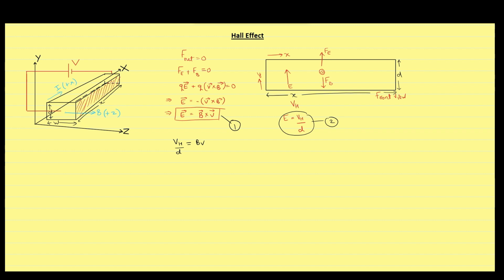v is the velocity of the charge carriers, we all know, but in terms of semiconductor, it is also given another name which you have already studied. This is nothing but the drift velocity. And you know that drift current density is equal to drift velocity multiplied by charge multiplied by charge carrier concentration. Here, C is representing charge carrier concentration.